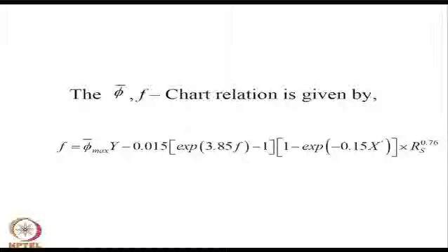The whole idea is, assuming that this correlation is valid, the correlation may not know where that number phi bar max is coming from. It may be from a south facing surface or a non south facing surface. So, if you have a method to calculate the monthly average daily utilizability for concentrating collectors or non south facing flat plate collectors, perhaps the same correlation can be utilized using your phi bar max as the appropriate phi bar.